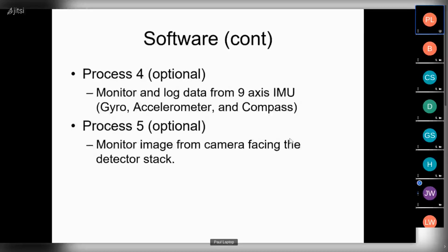If you get into these problems of saturation, I think these things generally use photodiodes with current to voltage converter amplifiers, just kind of an op amp, not a big deal, but you get a lot more dynamic range, probably like 6 decades of dynamic range instead of maybe 3 out of a phototransistor. Okay. So it might be worth looking at.